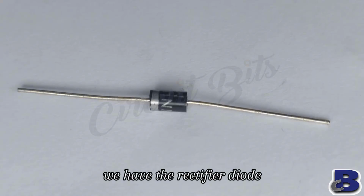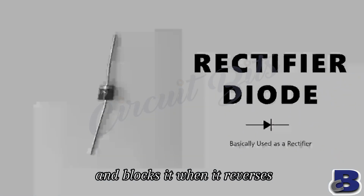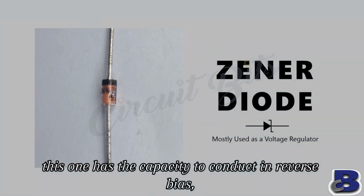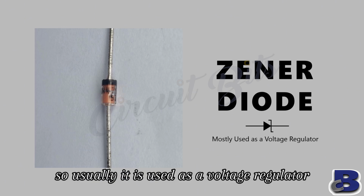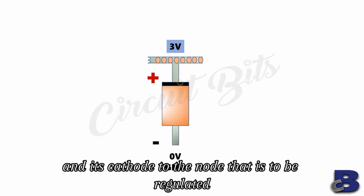We have the rectifier diode. They allow current flow in one direction when forward biased, and block it when it reverses. That's reverse biased. There's also the Zener diode. This one has the capacity to conduct in reverse bias when a specific breakdown voltage is reached, so usually it is used as a voltage regulator by connecting its anode to ground and its cathode to the node that is